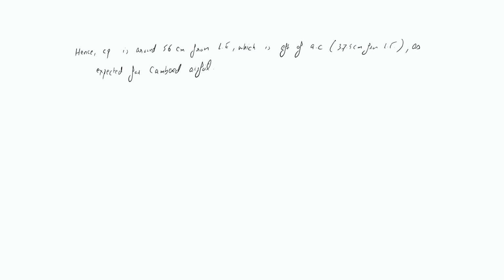Now there is another point. As CL is increasing, the CP should move towards the aerodynamic center, which we will show from the MATLAB plot. So let me quickly go to MATLAB now and demonstrate this result.